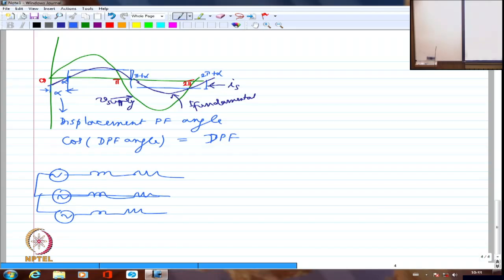So whenever I connect an induction motor, or anything which requires a sinusoidal supply, they are all going to get these harmonic voltages injected into them, which is not good for the induction machine, because we analyze the induction motor assuming a sinusoidal supply.